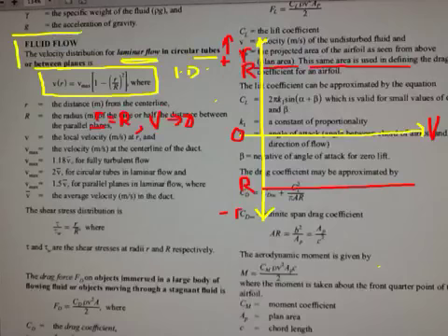So at those points on this graph, the velocity is 0, and otherwise, when the little r is 0, we have the maximum velocity. So this is V max, and the distribution is basically a parabola, and I'm doing a terrible job of representing a parabola, but this is the locus of each of the velocity vectors as a function of r.